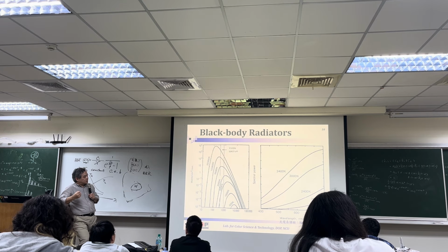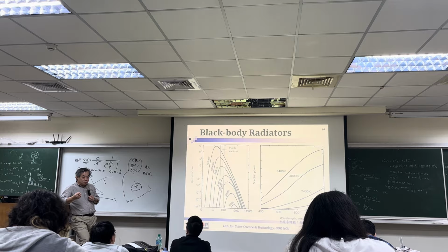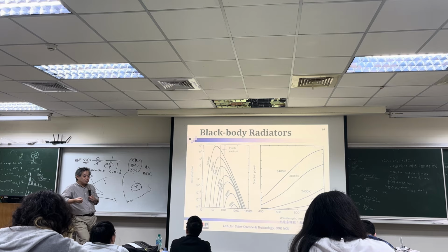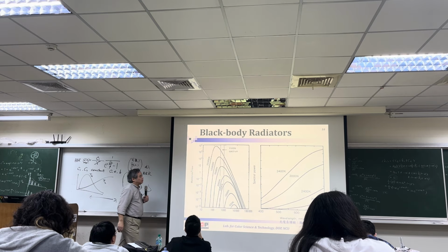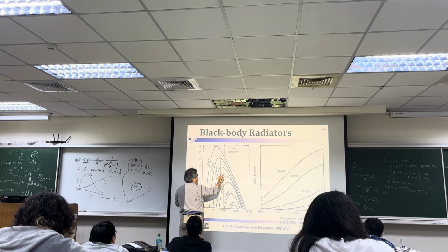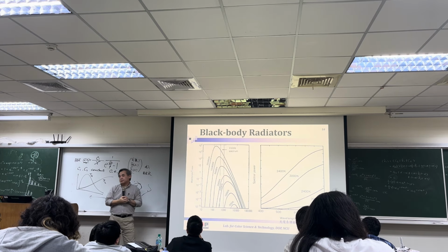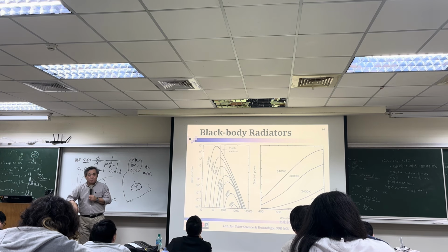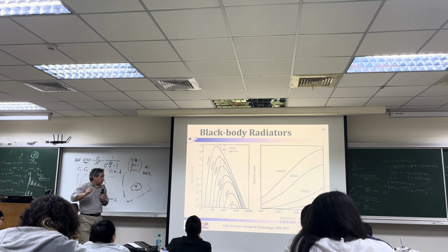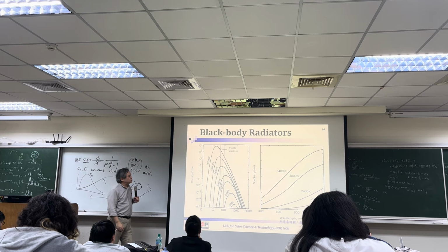So we will feel that when the light source is 5,000 K to 7,000 K, the color of light looks close to white, right? Because within our visible band, the spectrum is more flat, more like equal energy. So the color of the light looks very close to white. Okay.